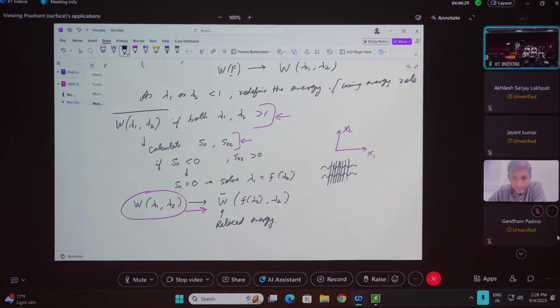Sir, if we are considering a pre-stretch initially to the membrane, we can anticipate that when we apply the voltage to that, wrinkles will develop in the direction parallel to the direction of the pre-stretch, because in the other direction stress will vanish first because of the application of the electric voltage. Yes, that's true. If you've already increased the level of stresses in a certain direction, then in the other direction you can expect the stresses will tend to 0 earlier. So it's all about trying to predict in which direction the stress is going to be 0 first, and that would be the direction where it will start getting wrinkles.